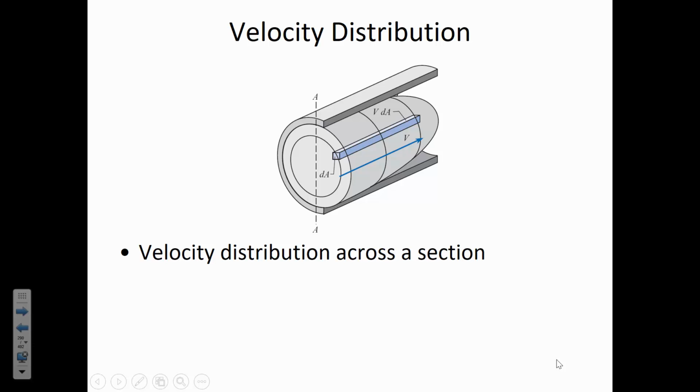Here's what I was talking about earlier with the effective laminar flow. And you can see that this velocity profile is bullet shaped, where the velocity is the highest at the center of the pipe and lowest going all the way down to 0 where the fluid is in contact with the pipe itself. And so the no-slip condition says that a fluid can't slip with 0 friction across a stationary surface unless it's an inviscid fluid, and those don't really exist.